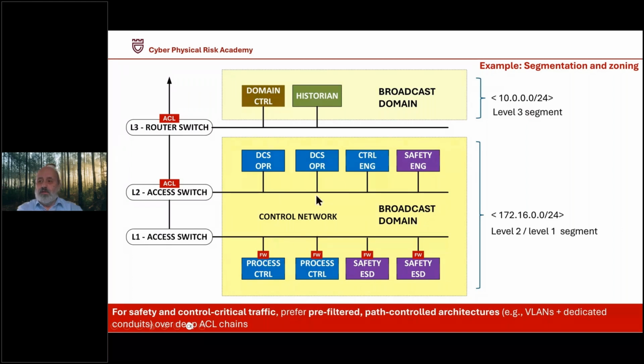If you look at a site, there is a lot of I/O in most plants, and a lot of messages, and it's really in this area where the real-time part is very important, because I can have control loops divided over multiple process controllers, so that I have a primary loop in process controller A and a secondary loop in process controller B, and that connection can be over the wire. It can be over the soft wire, let me say it like that.